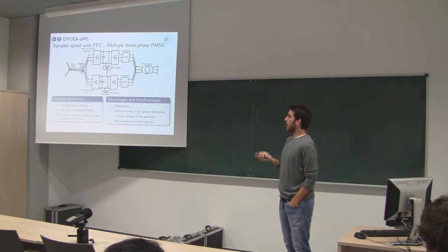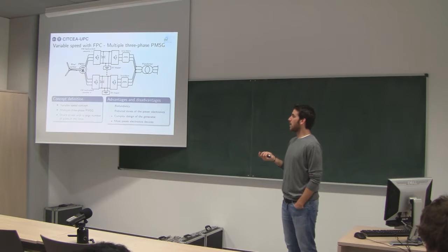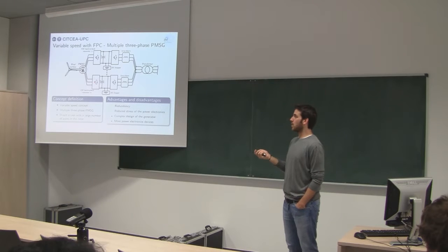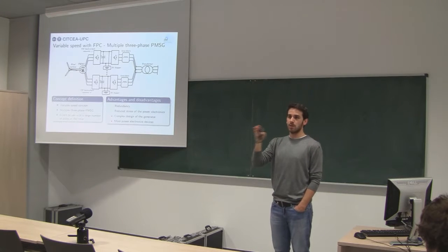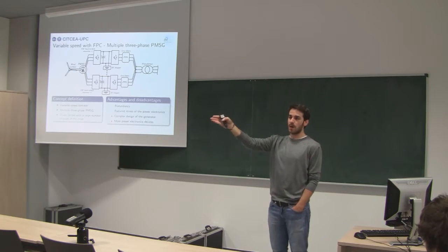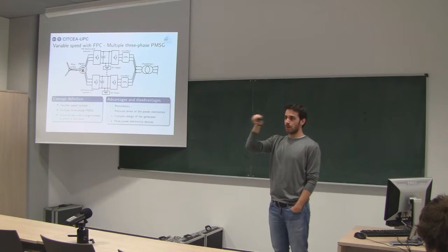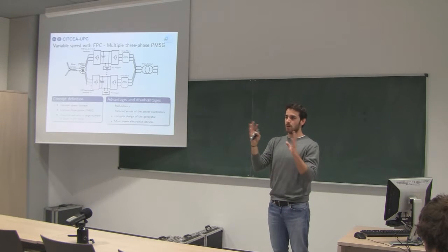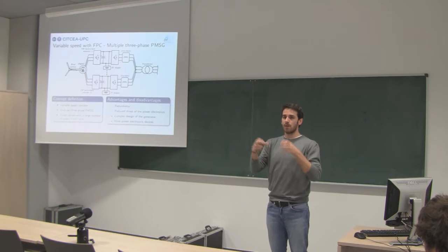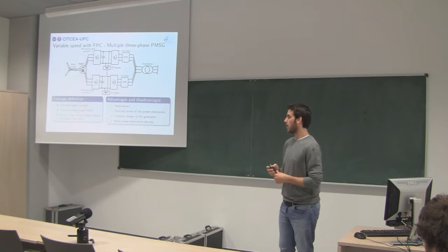Then it also has some benefits. They can reduce the stress on the power electronics. You have to imagine that if you have only one converter, all the current must go through this path. But if you have different power channels, you can reduce the rating of the IGBTs there, or the rating of the converter, and instead of having one large converter, you could have 3 different smaller ones.